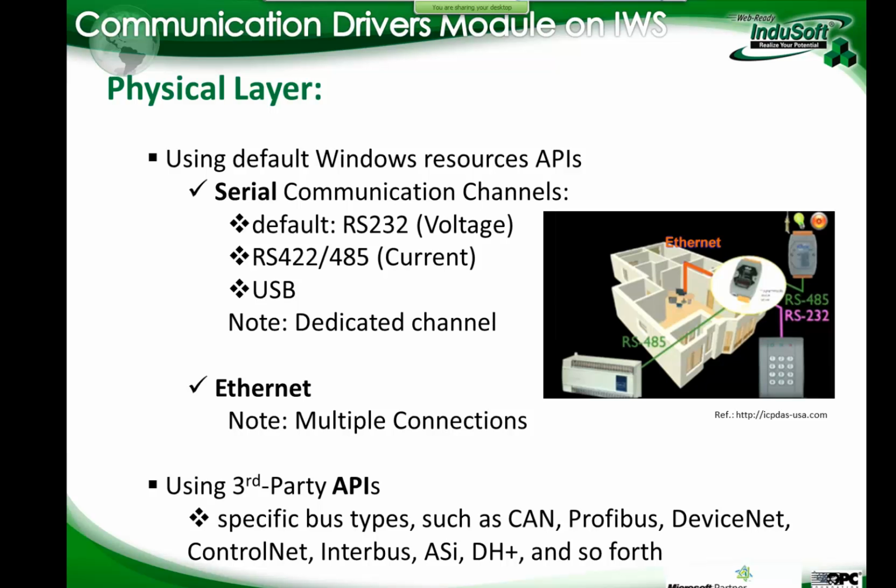A serial communication channel, most of the PLCs until, let's say, 2006, when you were going to buy a PC, you would get a serial port, DB9 there that would speak RS-232. Nowadays it's very hard to find that, but most of the PLCs, they had RS-232 communication channel, and to this day they still support that.